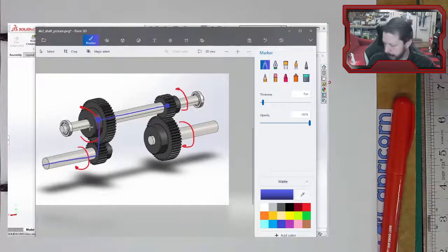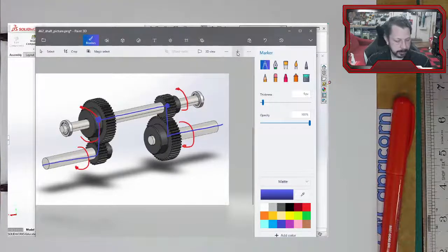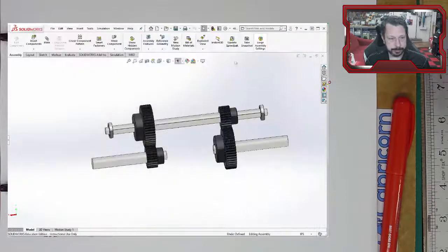So that same, what was it, 240 inch-pounds of torque that we just calculated on this larger gear is the torque on this smaller gear now. And we go through basically treating it like the input to this. So there's our torque path right there, what it looks like. And we're assuming that there's no losses anywhere, which is an okay assumption.